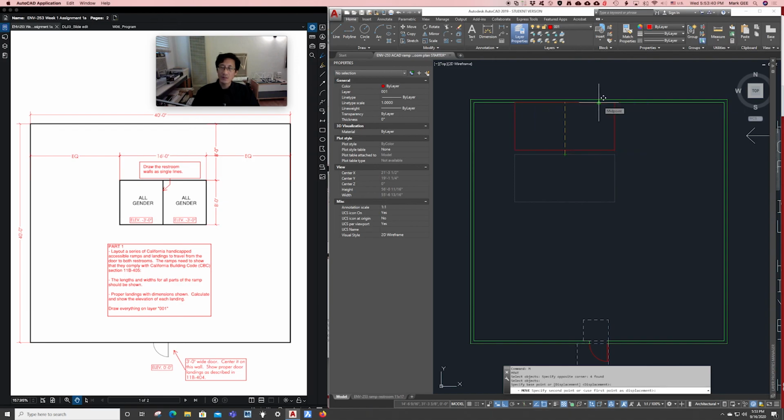It gives me the preview of the little green triangle. But the preview of the move vector there is still going straight up and down. The snap overrides the ortho. Sorry, the object snap. The midpoint snap overrides the ortho. So I can just click here, and it'll align those midpoints and override the ortho.